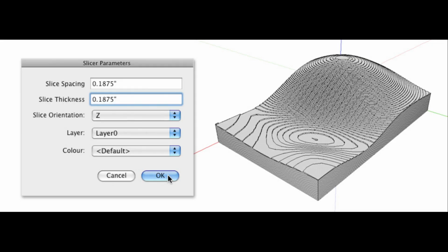Once the slicer has a usable model, the first major conceptual step happens: slicing the model into layers. This is not just "cut it every 0.2 millimeters." The slicer is intersecting the model with a series of horizontal planes. Each intersection produces one or more closed 2D shapes for that layer. Those shapes represent where plastic should exist at that height.